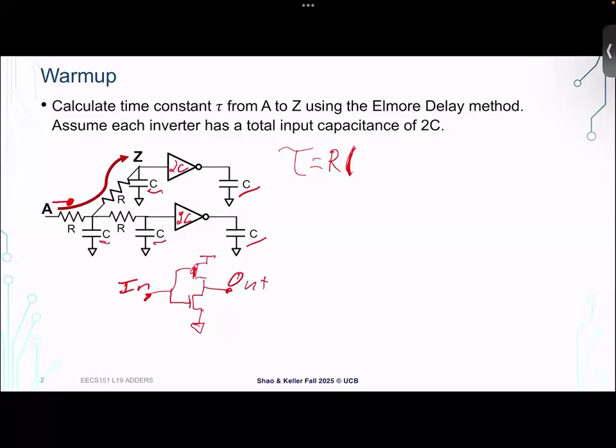Right, the gates of a transistor don't conduct current. They just are a capacitance. So you have to keep in mind that when you have current flowing at the input node, this is the end of the line. It's going to hit these gates and then stop. And then the current at the output node is drawn from VDD or sunk to ground.